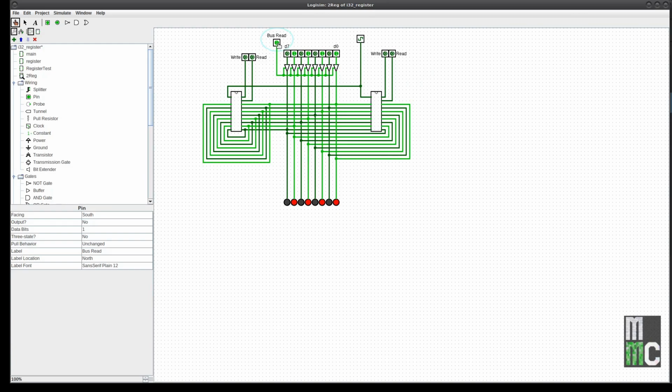Those are our outputs. Now the question is, can I put a value from, say, this register, which you see is the 4 inner, to this register? Certainly. Where do I want to read from? I want to read from this register. That's now on the bus. And of course, I want to write whatever is on the bus, and I just click this. And now the two registers will have equal values. You can see that no matter what it is, it's there. So I choose the bus, for instance. I choose the write here. I click the clock. And now I've stored the new value that is on the bus in this register. And that's all we have to do.